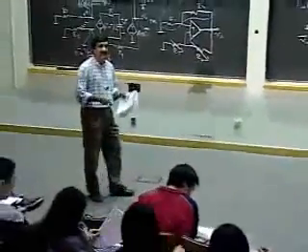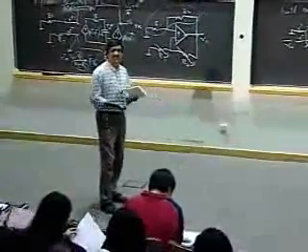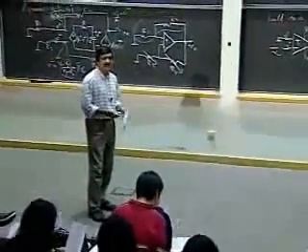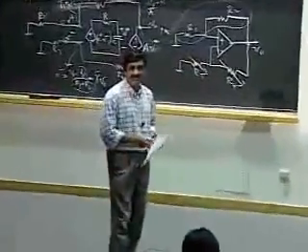So notice how the output switches at +6 volts, and then switches at a -6 volts to +12 or -12. Okay, that's a hysteresis property. And we can actually use this property to build a clock circuit, which is on page 9. Builds an oscillator that sits there and oscillates by itself. And you will see details of that in recitation tomorrow.